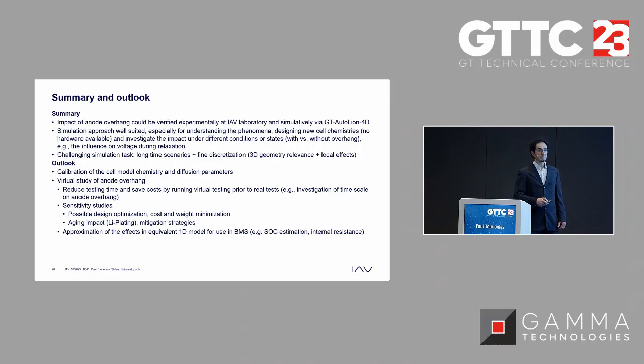And concerning the application cases, a virtual study of the anode overhang, for sure with the simulation we can reduce testing time and save cost by running virtual testing prior to real tests. And we can run some sensitivity studies, which can lead to some design optimization, cost or weight minimization. And one possible step is also to look at the aging impact.